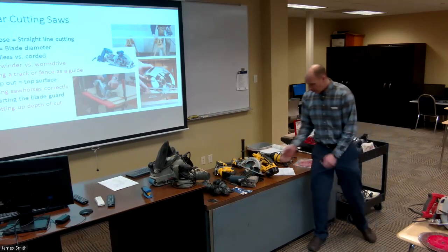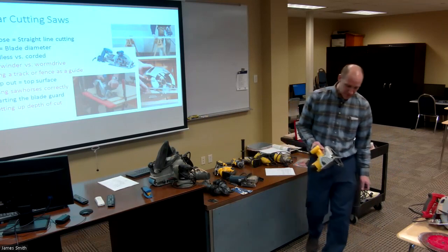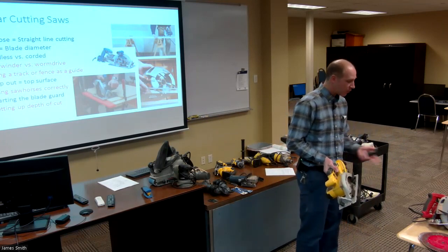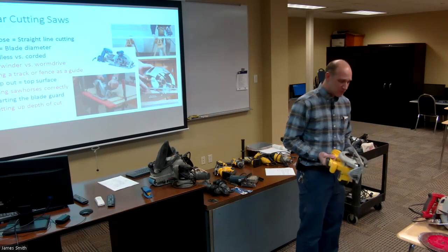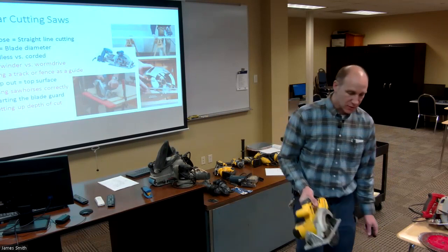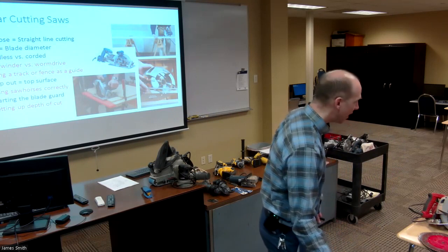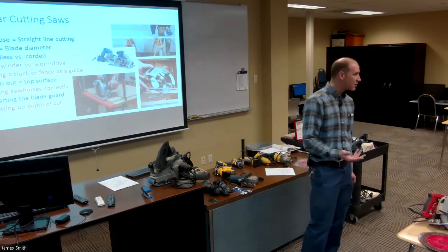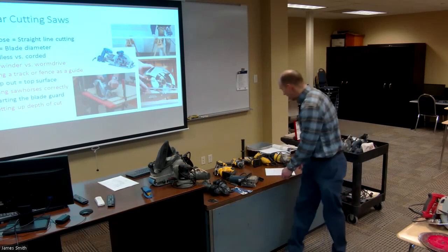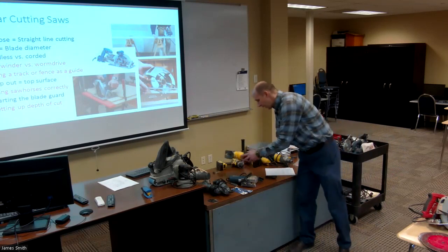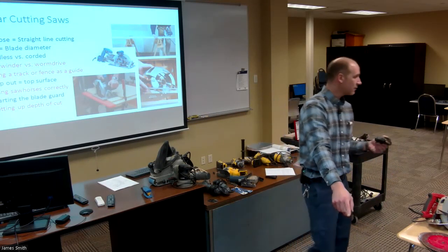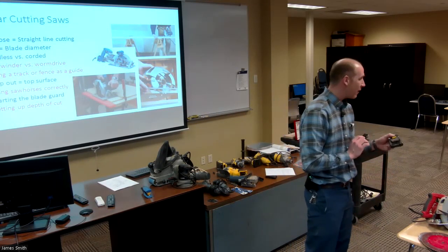When you're looking at portable saws like this, you've got the choice between battery and corded. For circular sawing, usually if I'm cutting an 8-foot long piece of plywood, that's a long cut, and it's going to take a pretty substantial battery. You wouldn't ever want to use a battery like this on a saw like this, because it's only a 1.5 amp hour.